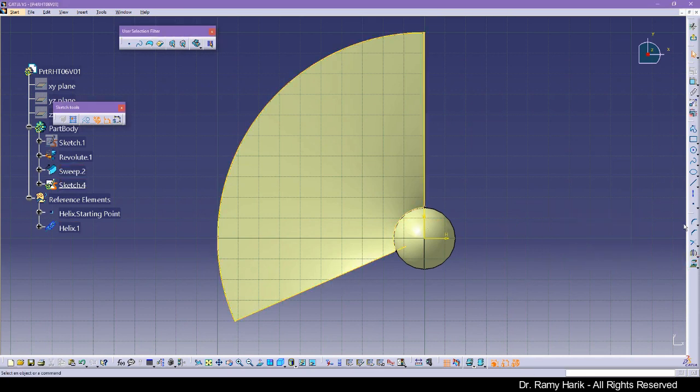Next thing, there are so many things you can do to remove this excess from here. You can use quick trim, you can use the break, the trim, wherever you think makes sense to you. So I'm gonna use quick trim here, and I'm gonna use quick, oh, I did not click again. So I'm gonna use quick trim here again.